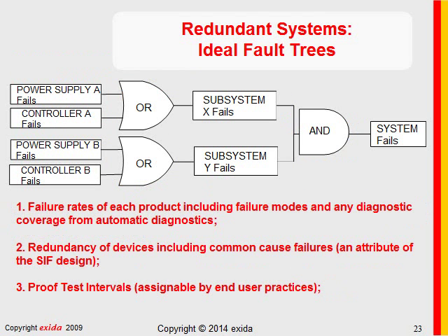Okay, now, what about redundancy? Many people will take these simplified equations and calculate probabilities, put them into fault trees, where we add up the probabilities if an OR gate is involved, or we multiply the probabilities if an AND gate is involved.